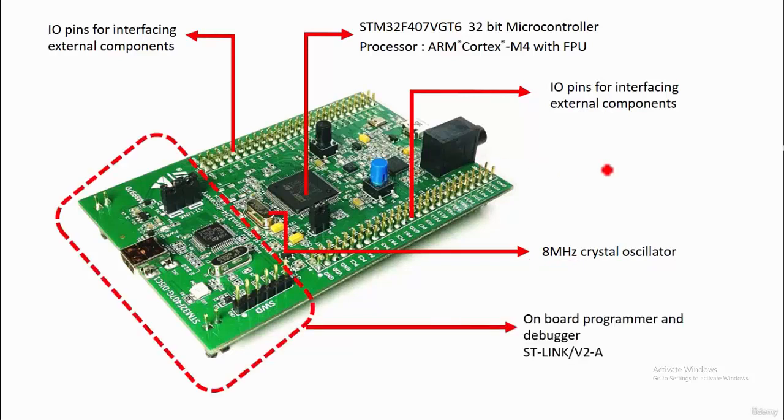Apart from that, another important feature of this board is its onboard programmer and debugger. This is one of the important features of this board. If you want to program and debug the code on this hardware, you need not buy any external programmer and debugger. The board comes with its own programmer and debugger, what we call ST-Link V2A. By using this onboard programmer and debugger, we are going to program and debug our code.